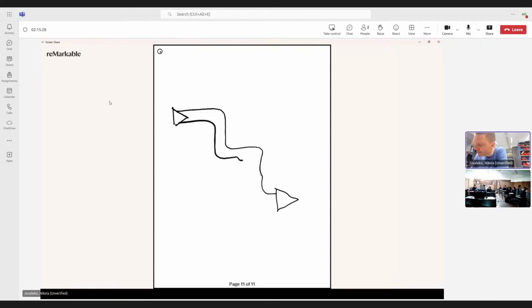And due to any obstacles, this line is longer. Then you will have a skew. You will have actually these signals shifted to each other. And your eye will not be open properly here, and you will not decode properly the signal.